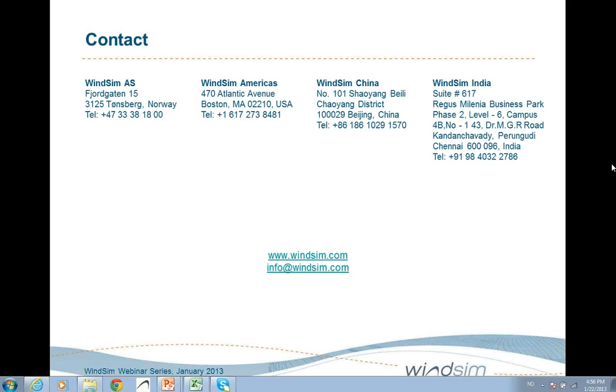Then we have another question. Can we include long-term data, more than 10 years, from near Met towers? And can we develop MCP analysis? You can include long-term data, of course. This is also required in WindSim, that you should include long-term data. Of course, these met towers should be within the simulation area, so they should be in the range of around 30 kilometers around your turbines, and they should, of course, be also a bit representative for the area where the turbines are placed.